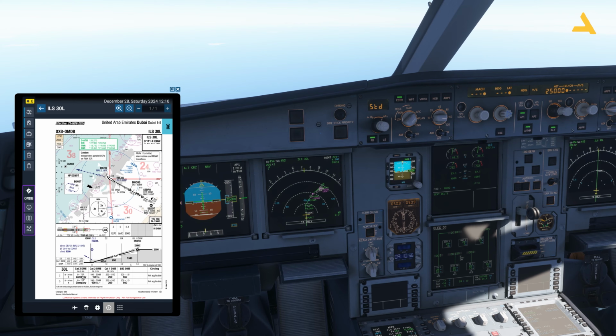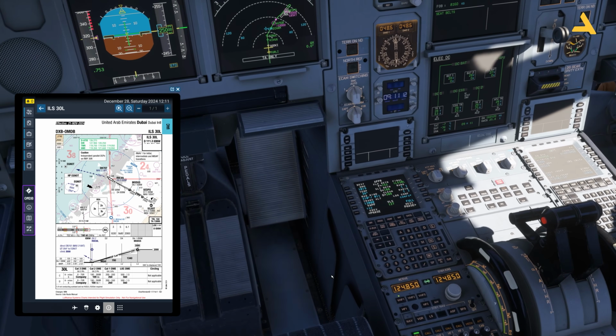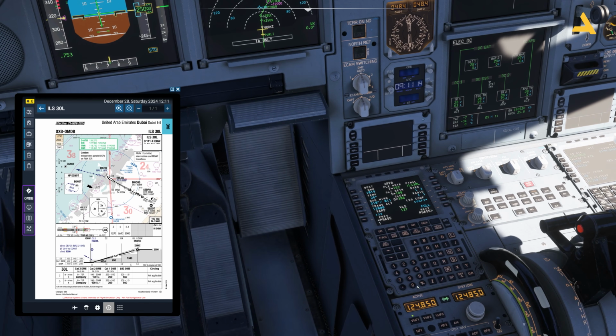So for radio, you can set 0 to 75 feet. Between this, it's given to you by the company. But over here, you can see for 2, this is 100 RA. So 100 feet above the runway, you will hear this callout, minimums, and you can decide whether you want to go with it or not. So let's keep it at 100 for radio, and that's it.